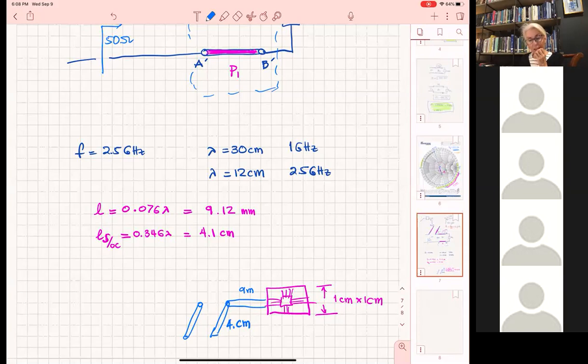Huge. Horrible, right? Because in reality, you want to make everything so that you can materialize it. And so it's going to be difficult to do it like this, which means that I will have to remove this. As a matter of fact, it's also going to look kind of weird, because the way to connect a series stub in microstrip is kind of tough. But in any case, the length is unacceptable.